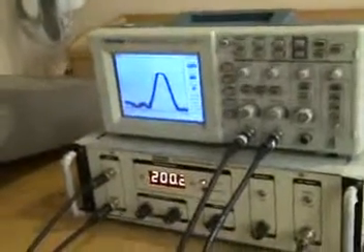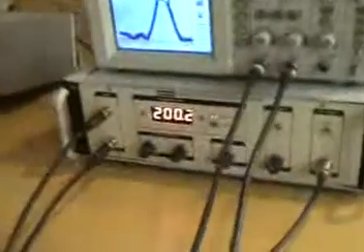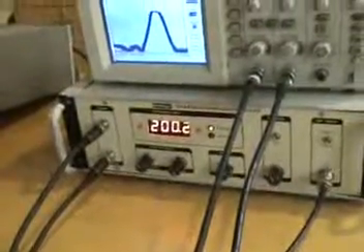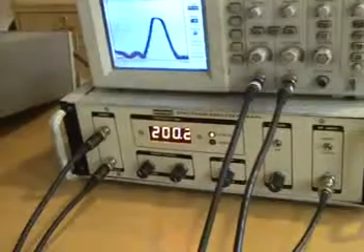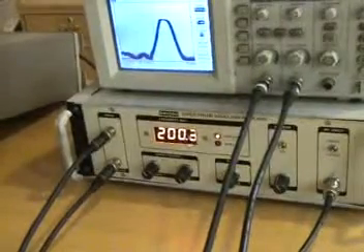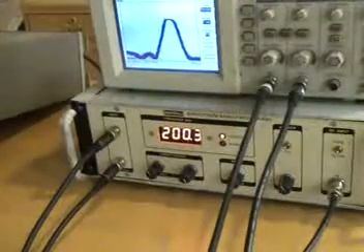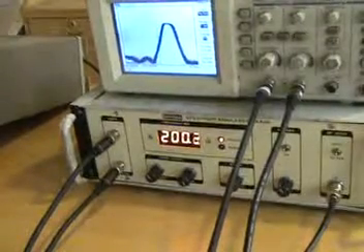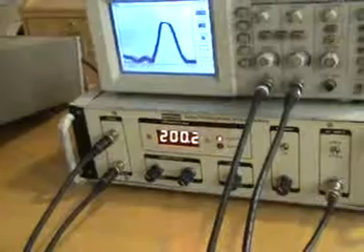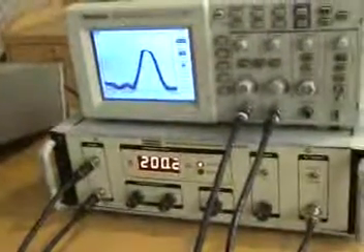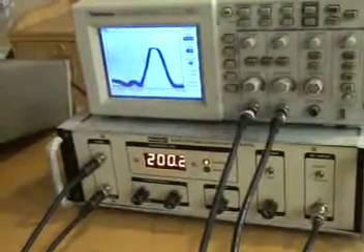The resolution of the frequency display is 100 kilohertz, whereas the scan width is much better, around 10 kilohertz, and the display is of course 4 digit here, and we are using 40 dB and 20 dB attenuators to read higher amplitude or high power signals.